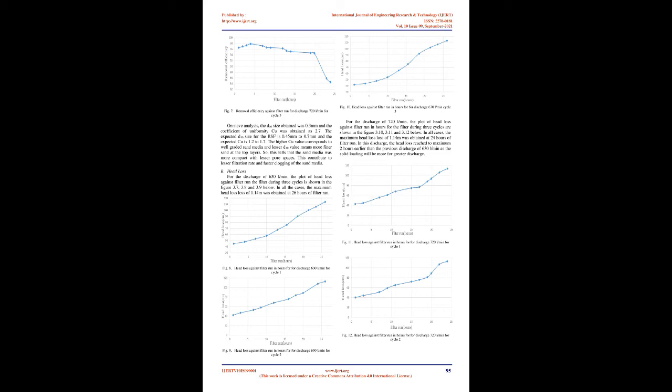NTU solution. The cuvette was rinsed with distilled water and again with the sample and then the turbidity of the sample was measured. The 0 set and 100 calibration was checked in between the readings. The turbidity values for both influent and effluent were taken several times during the filter run. The filter run time at which the sample was taken was also noted.